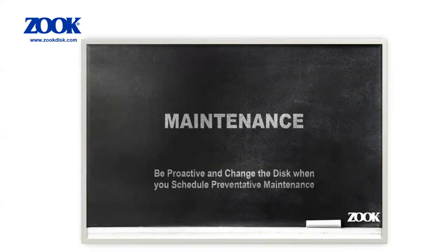People ask us all the time, how long will my rupture disk last? The truth is nobody knows, and scheduled preventative maintenance is recommended. Or if the process is down, take the opportunity to change the disk out. In absence of actual installation history, we suggest starting with a 1-year interval between scheduled disk replacements.